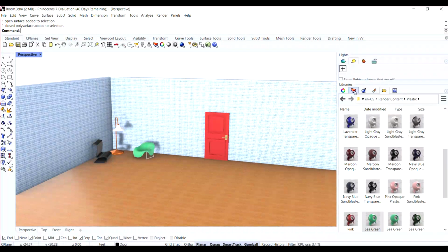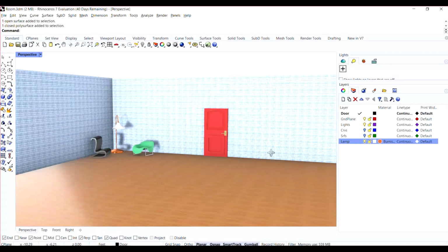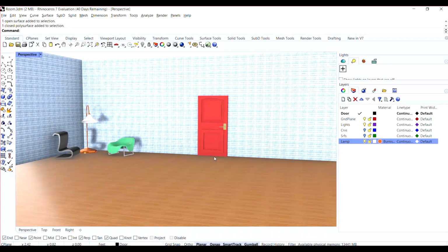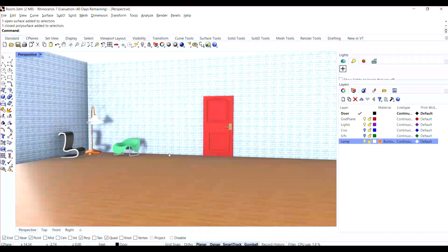So recap, you can add materials by each part in material properties, or you can design the materials on a group, place them under a layer and add material to a layer. That is a very straightforward way of doing it. You can create your lights, your ground plane, curved surfaces to back up your design in case you need to replicate, modify, or recreate parts.